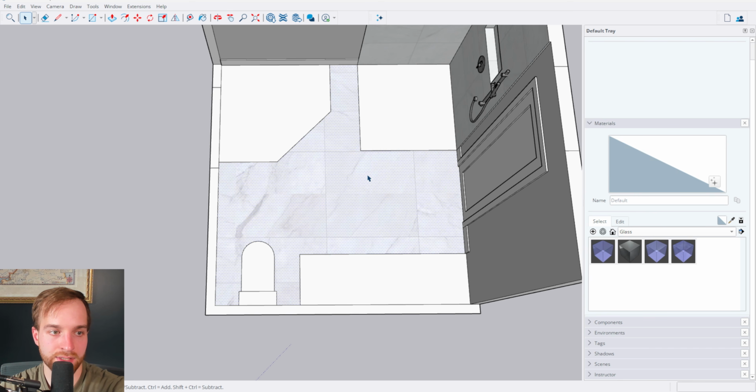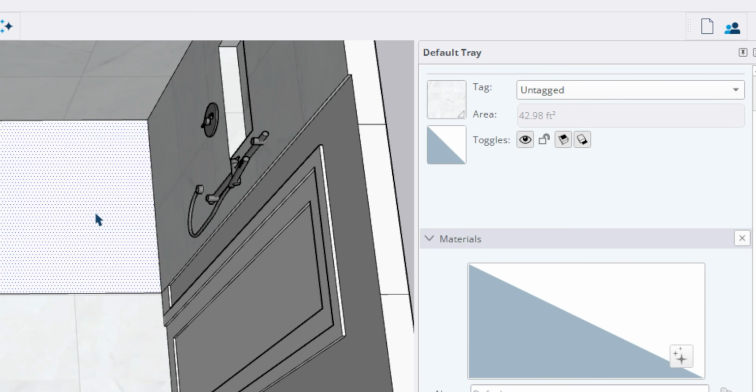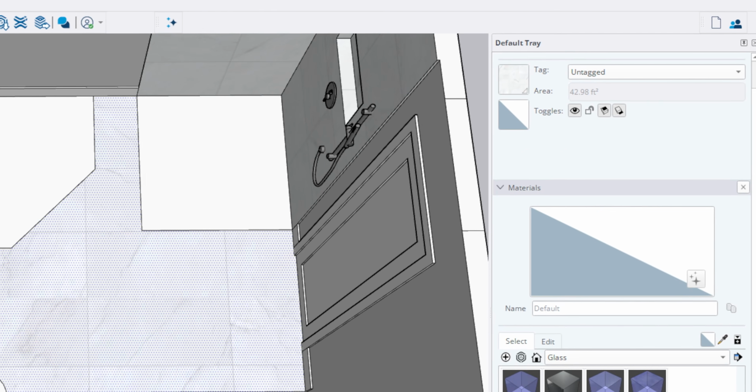So I can just select this now, and just like that, it'll generate my square footage. So 43 square foot. Let's say I'm using Schluter Ditra-Heat. I'll find the heating cable that is closest to this number, and then I'll just get that cable. And then if we wanted to do, say, a heated shower floor, we could just click this and also get a number for that. So it makes it really useful in this regard.